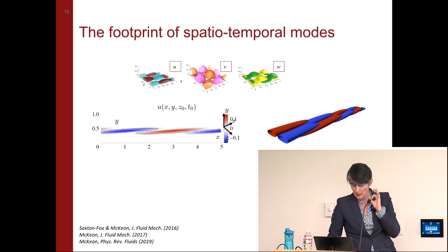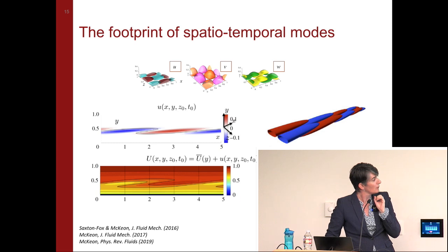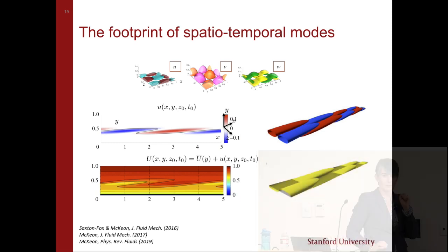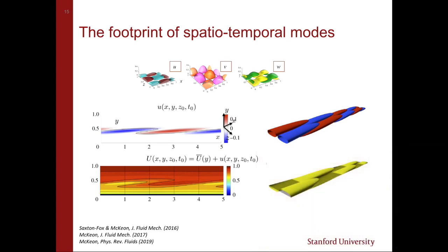Now, if I add in the mean profile, I'm going to see this type of effect. Even though I have something that looks very symmetric about the critical layer here, when I put in the mean, and I haven't specified the relative magnitudes for right now, so this is an example only, I end up getting these bulging structures, which look like this in 3 dimensions. This is the deflection of an isovelocity surface.